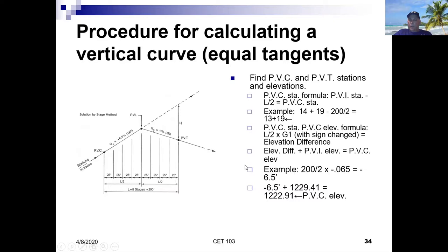The concept for calculation of a vertical curve is actually fairly complex, because the vertical curve, unlike the horizontal curve, is not a simple curve, it's a parabolic curve. So therefore there's a constantly changing radius along the way. So I encourage that you follow the processes and procedures, which will come at a later class, which will talk a little bit about how to calculate a vertical curve. But I do want to start with, how would you find the grade of at least the beginning points and the ending points of this curve?